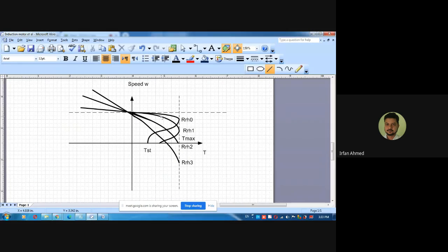Of course, nowadays, with the advent of inverters and cycloconverters, it is possible to change the synchronous speed so that you can get regenerative braking at any speed. But at this point of our syllabus, we are not using any power electronics. So regenerative braking will be possible only when the speed is greater than the synchronous speed.